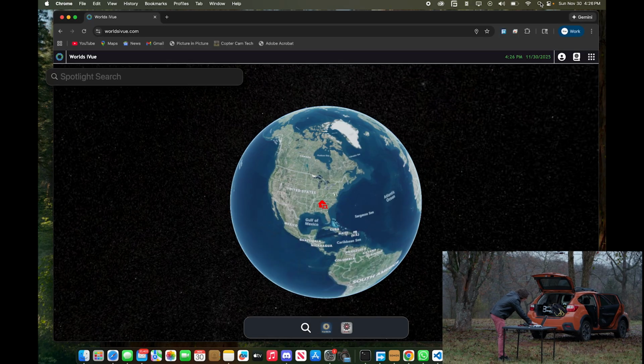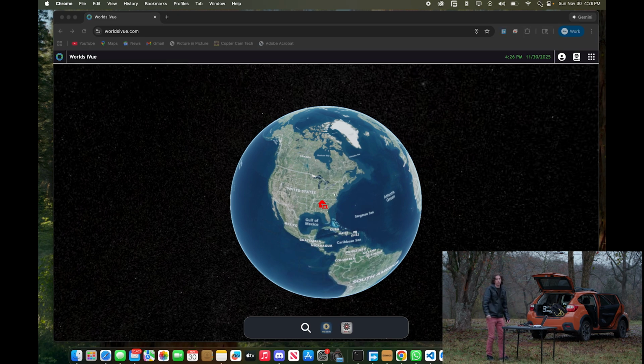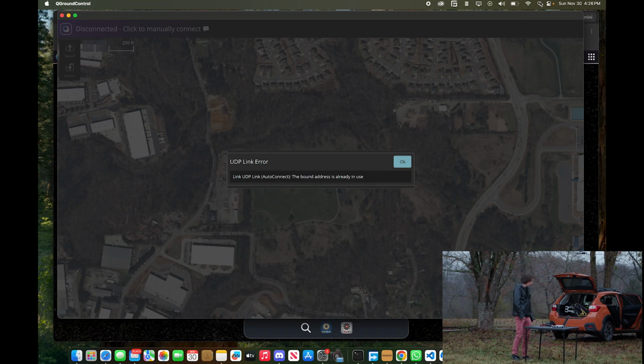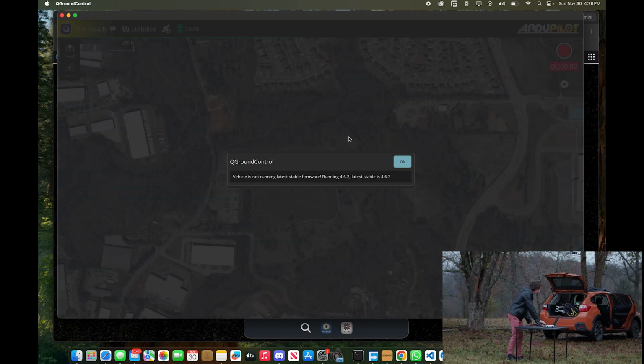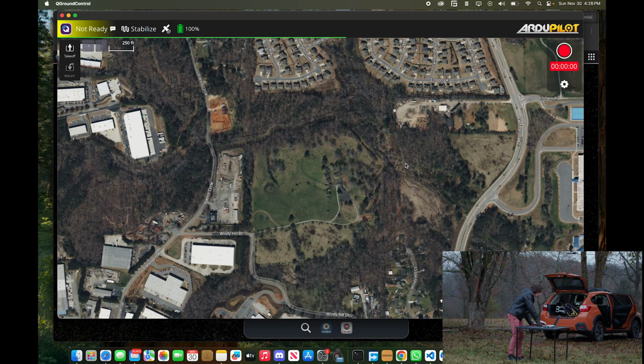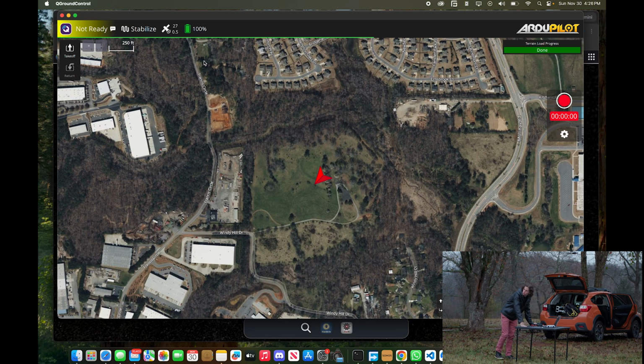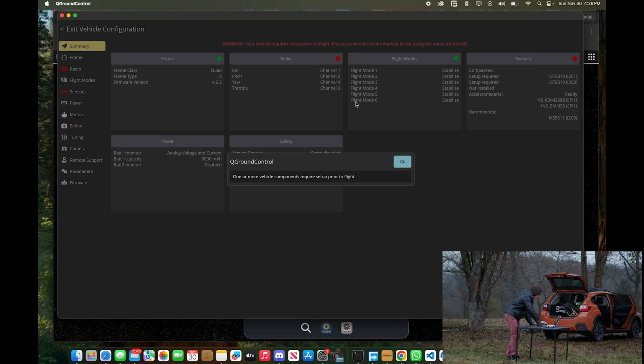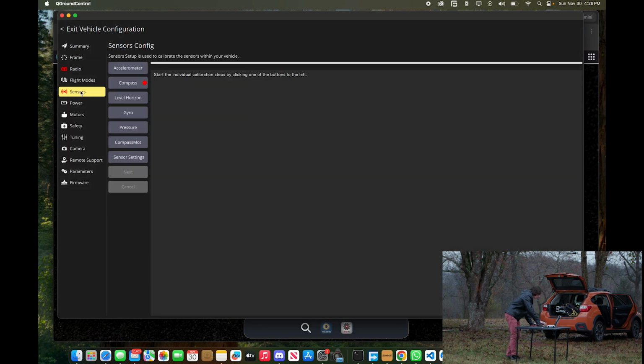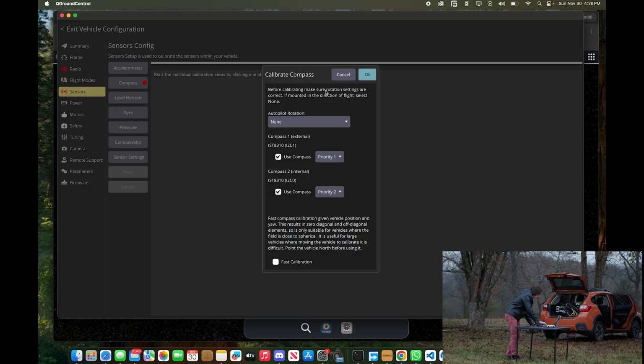Looks like we are getting some sort of bug where you should be able to go directly from the accelerometer calibration to the compass calibration, but we got a message indicating the compass calibration was done when it clearly was not. So hopefully that was just indeed a UI bug of some sort, or a ground control software bug, QGroundControl bug, and not a hardware problem.